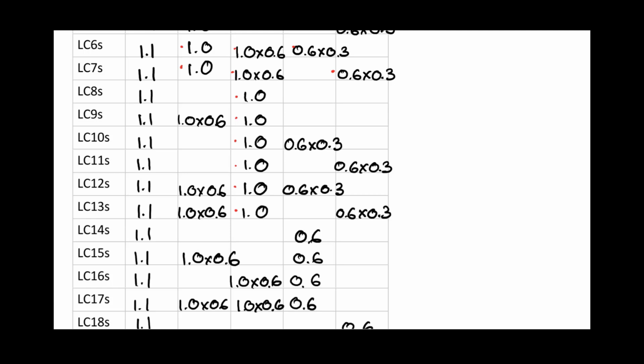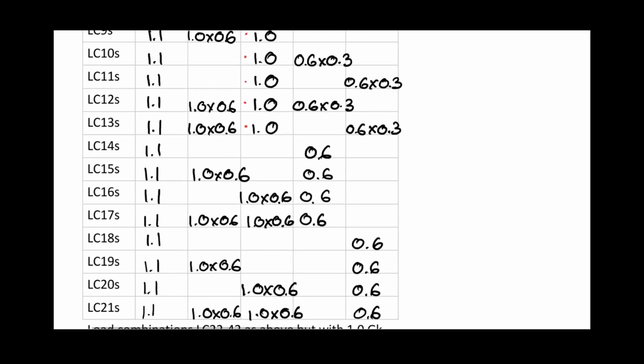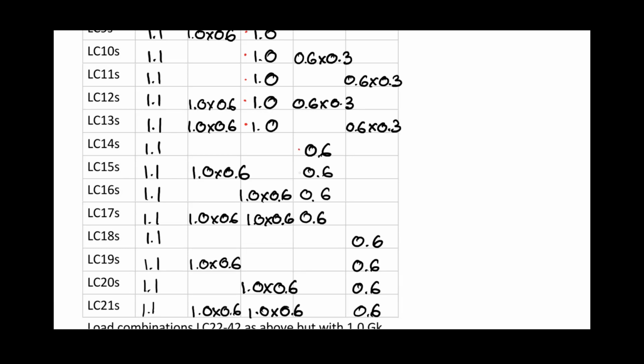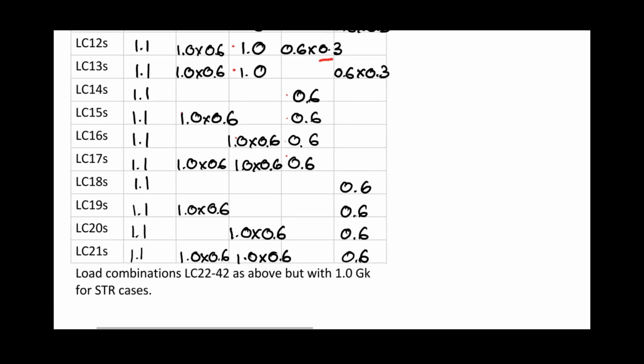And here you'll see for all of the wind, once again, I do not have W1 and W2 acting at the same time, and then I have the wind load leading, no combination factor, so that disappears, it's just the pure partial factor. Combine it with imposed 2, both of them, same thing for W2. Go through and get 21 serviceability combinations, and then you'll see we have to do this all again, but instead with 1 times the dead load. So that would be then for when the dead load makes the load less.